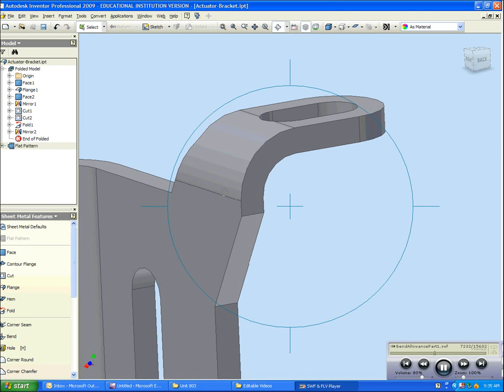Now the opposite is going on underneath. That part of the object is undergoing compression, and this actually deforms the object, and these parts that you're concerned about being in a certain place may move. So what you actually have to do is take all this into account when you're doing your flat pattern, to make sure that when it's bent, everything is in the correct place.